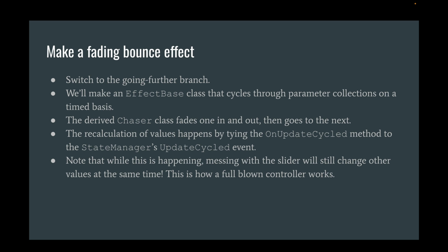One goes after the next, and we do that by way of the timer letting us know that the update has cycled, and by that we're recalculating where in the sequence we would be. So let me explain what that means exactly. If our delta, for example, is 1 second and we're halfway through the second, then that means that our fade would be exactly between 0 and 255, and it would calculate that.